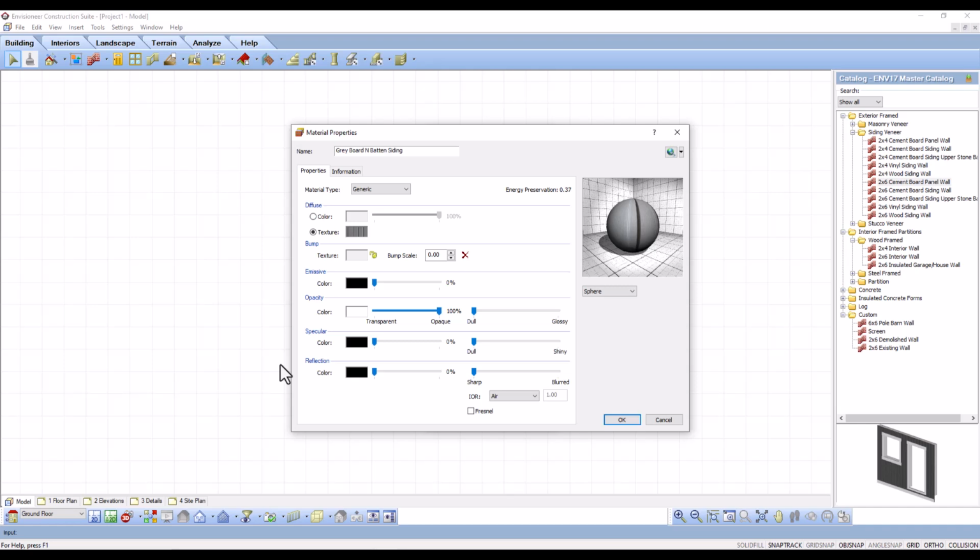The IOR, or the index of refraction, describes the way light bends when crossing the material surface. A value of 1 means that the light will not change direction. Selecting a material from the drop box, be that air, water, crystal, diamond, will populate the IOR edit box with the index of refraction for that specific material. If you would prefer to specify a custom value, you can select the custom option, and then in the edit box you can type in whatever value you want for the IOR.